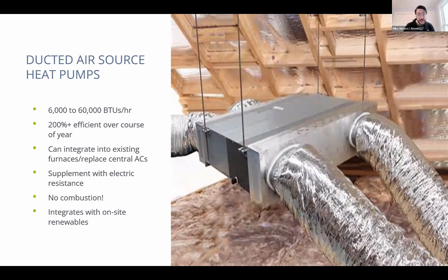We also have ducted air source heat pumps. We'll look a little bit more at this, but do know that there are subcategories within this category. There's the US equipment, there's the Asian equipment, there's the little units called low static, there's medium units called medium static. Those two could also be referred to as slim duct. That's sometimes a vocab that installers will use. And then there's high velocity systems, which look exactly like a fossil fuel based furnace, but no combustion is taking place.